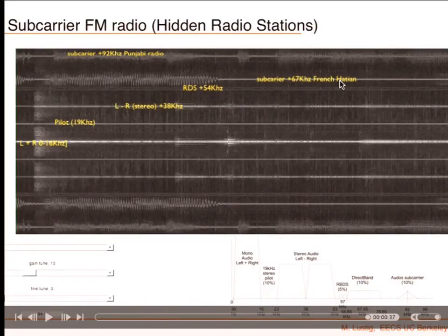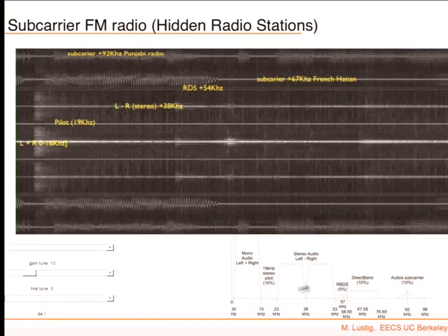Okay? Yeah. For the stereo, what do you have, two trapezoids on the graph there? Yeah, because it's AM, amplitude modulation. When you amplitude modulate, you take something that has two bands, and it's translated, right? That's the positive and negative frequencies. Actually, all the information is here. You could use just one band, but it's much simpler to demodulate this way.